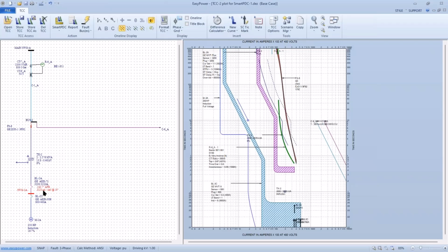So our instant energy almost doubled. It went from 18 calories per square centimeter up to 32 calories. That's testimony to the fact that coordination very often contradicts mitigation. We're not talking safety, we're talking reliability of the system.